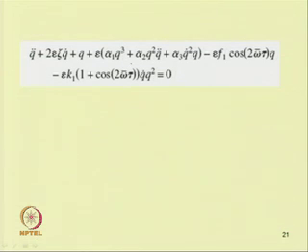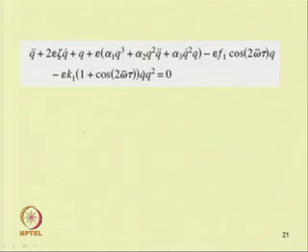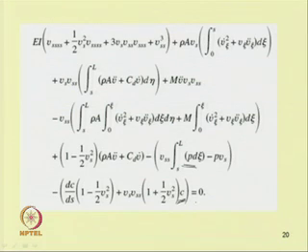By taking a known shape function or a known eigenfunction of the system, one can easily find these coefficients and convert this equation in space and time to the temporal form. So, to apply the Galerkin method, let us consider this equation. If one substitutes V equal to, let us take only a single mode, psi(x) and q(t), and if psi is not a function which satisfies the differential equation of motion, then there will be some residue left in the equation.